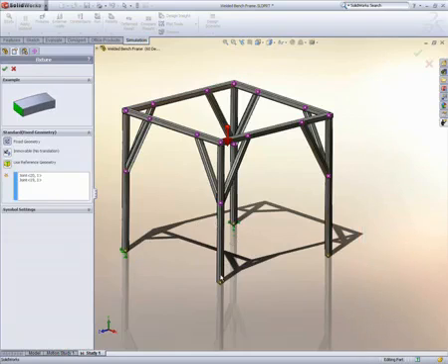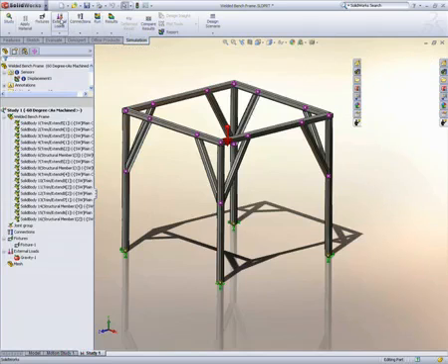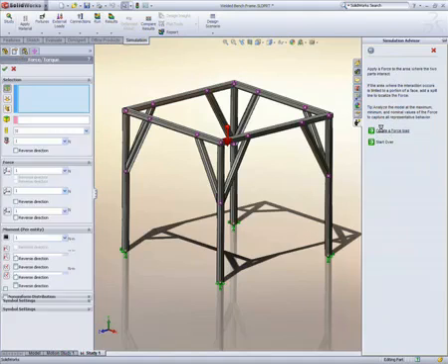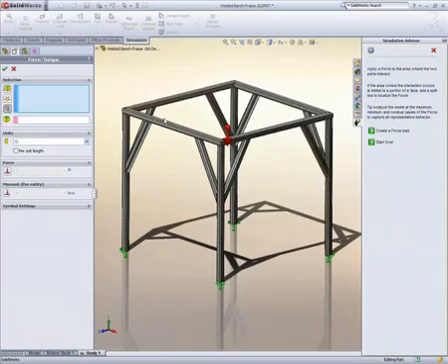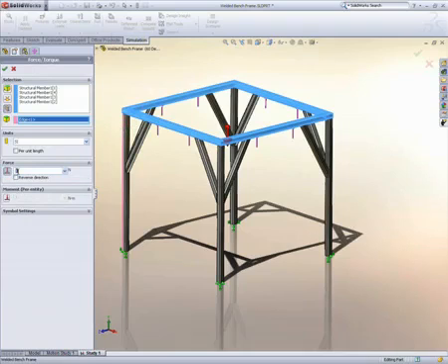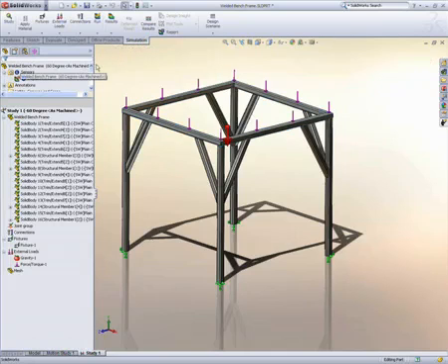All we have to do then is identify the points where the frame is restrained. Similarly, with the loading, the advisor guides us through the decision on if we need to include the bench top applying the load to the frame. In this instance, the bench top is far more flexible, and we're advised to just represent it as an applied force. The advisor automatically generated the load condition. All we have to do is specify the amount and the direction. Here we are selecting the weldments the load is applied to and the amount of load on each weldment.